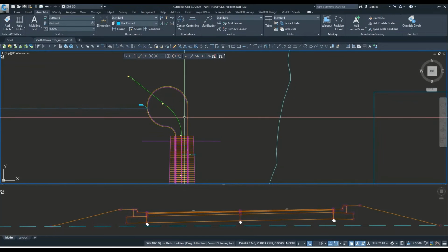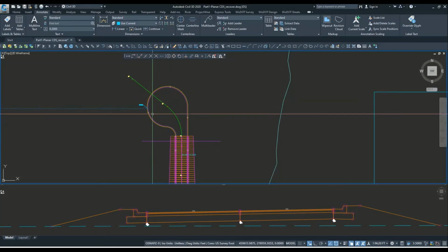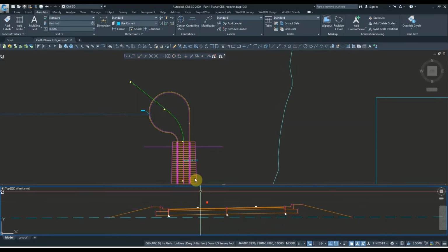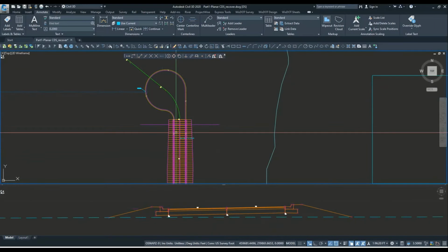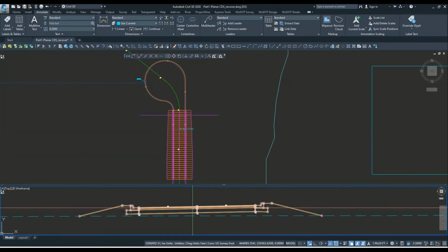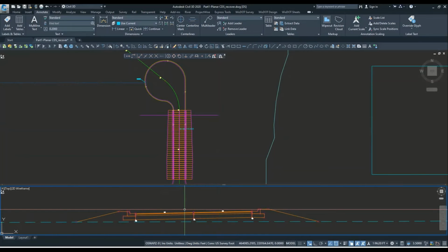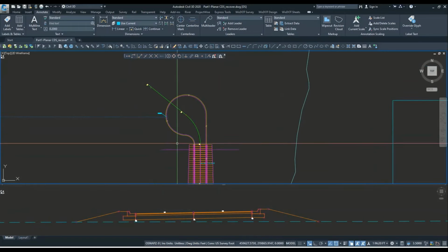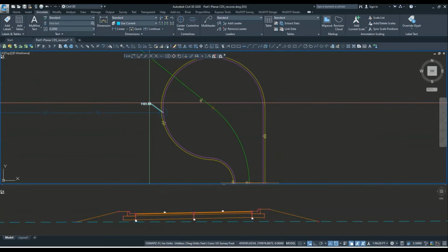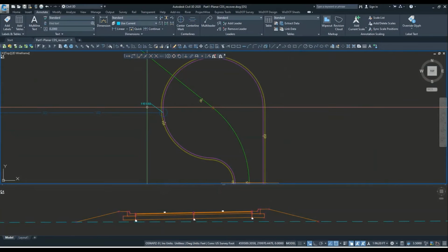So like I was saying, we're going to be designing first the planar cul-de-sac and then a crowned one. And for the thing I have modeled down here already, the throat of the cul-de-sac, I'm showing below the cross section, and as you can see, everything is straining to the left because eventually we want to get it to this structure with this spot elevation, or not spot elevation but target elevation.